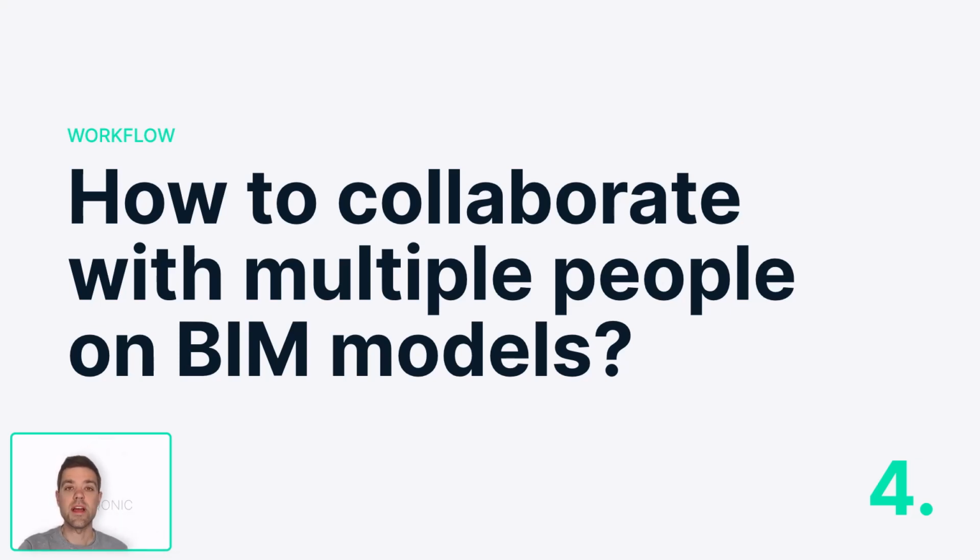The next workflow that we would like to demonstrate is how to collaborate with multiple people on BIM models. Of course, a design process is highly iterative, and that's why we've built in a versioning system that is very similar to Git, which can be used to collaborate on projects with multiple people together. The basic idea is that there is one central public model that is available for everyone, and everybody can make changes in their own personal version of that public model. These changes can then be published or synced so that they become available for every other stakeholder that is involved in the project.